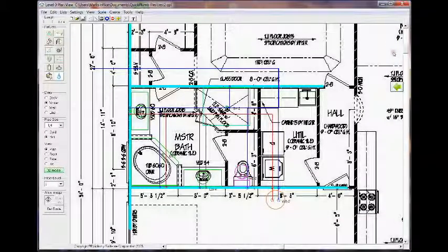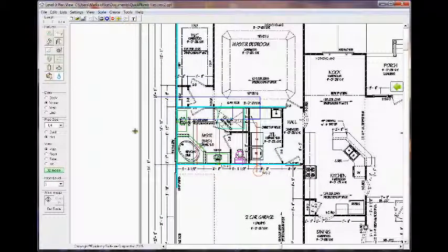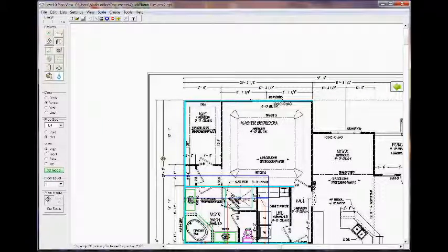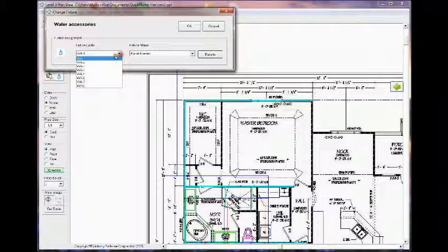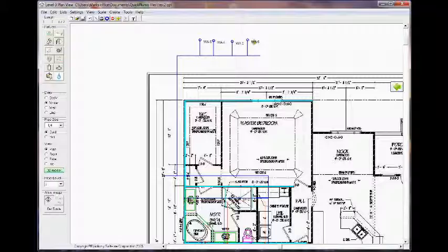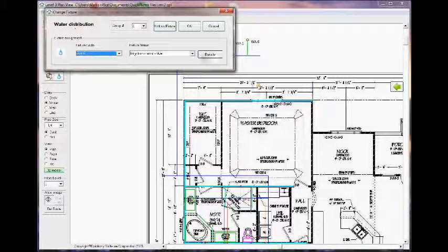We can also check the effects of adding a sprinkler system to the water main by teeing off the water main and dragging irrigation valves and sprinkler heads onto the project. When we right-click a control valve and select Properties, we see that we have a group setting.